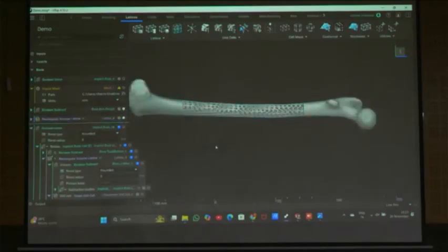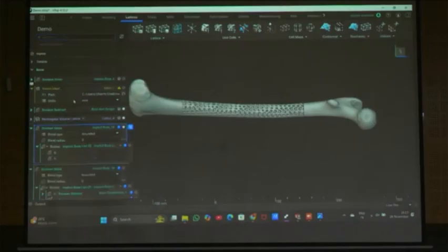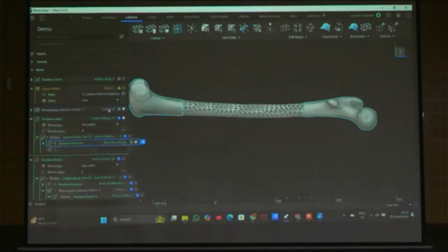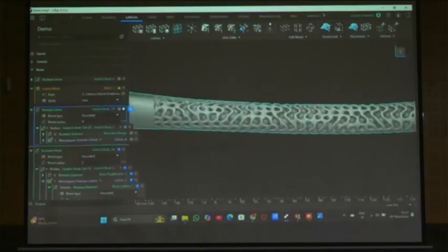Now again same thing, same operation. We have completed this tensile operation only. Again once we are getting this, we can combine the two bodies, right? So Boolean union. There is some one part is there, intersect is there. Intersect means the common portion we will get, okay? So two bodies we need to combine, okay? See, we have combined the two bodies.